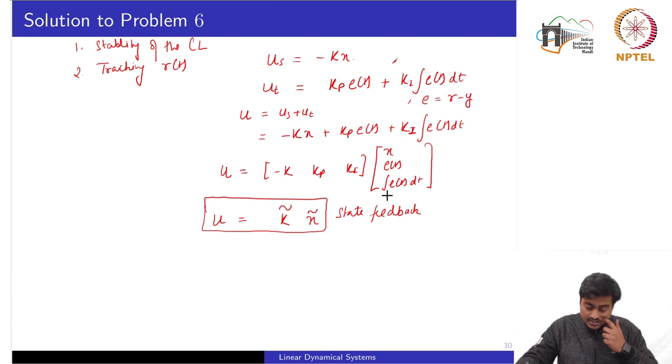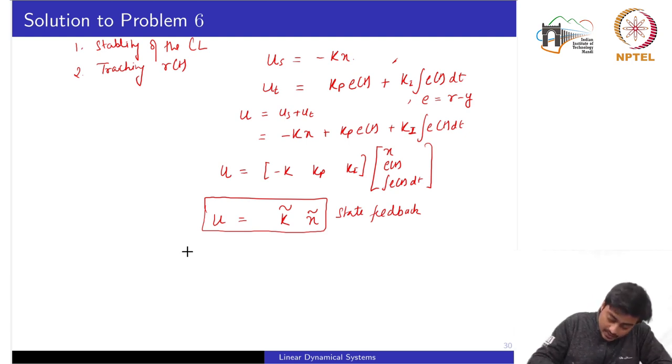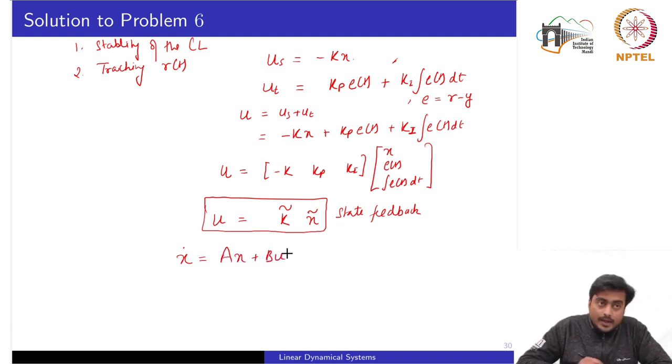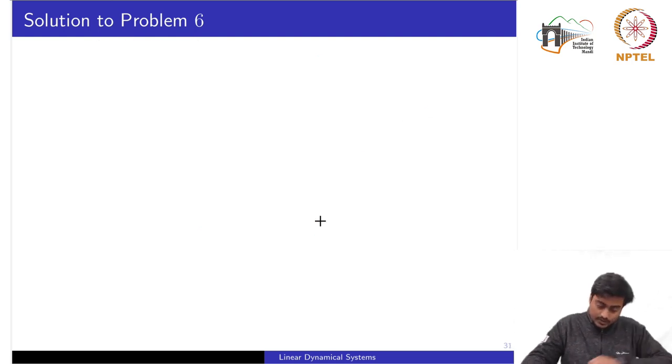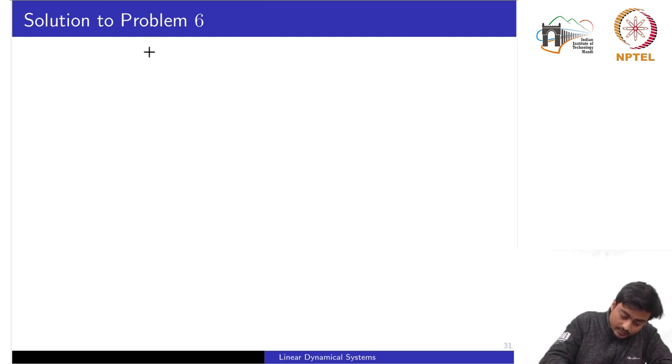Now, since this is a state feedback, and if we see that our original plant is given by this one, and we need the state as x tilde instead of x to finally design this k tilde matrix. So we will parameterize our plant into this new state variable which we are defining as x tilde. So let's write a couple of equations.